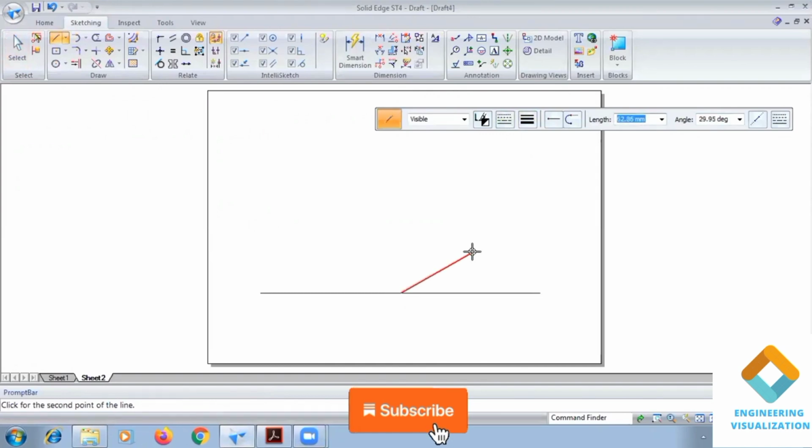From this reference end, the length will be 50, angle is 30 degrees. Again length is 50, angle is 150 degrees. Then again length is 50, angle is 210 degrees. So like this we need to construct the box. Now for the vertical height we need to give a height of 50 mm. One line I will draw, length of 50 mm. Then go to the move command, create a copy of it, or you can directly do it like this. Length 50 mm, we can do it directly.